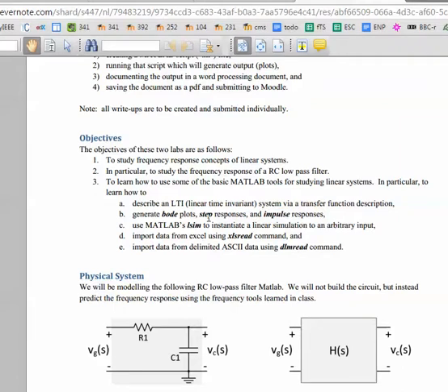does several things. It will use the description of the Sallen-Key filter to generate some plots automatically. That is the Bode plot, step response, impulse response. It will run a simulation using LSIM to predict the response of the filter to a square wave input.